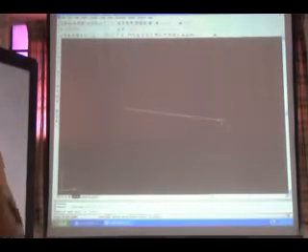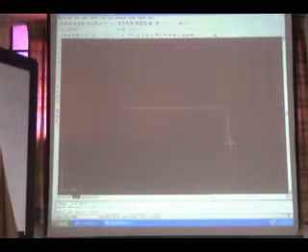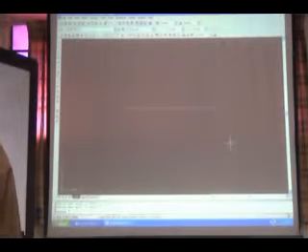Suppose I want only horizontal, vertical, you have a command. Purely horizontal and purely vertical, so that is F8. It's ortho. So I can draw orthogonal lines, only horizontal and vertical lines. You see, this is a horizontal. So just by ending that, I have drawn a reference line. When you are drawing, it's over. A reference line I have drawn.